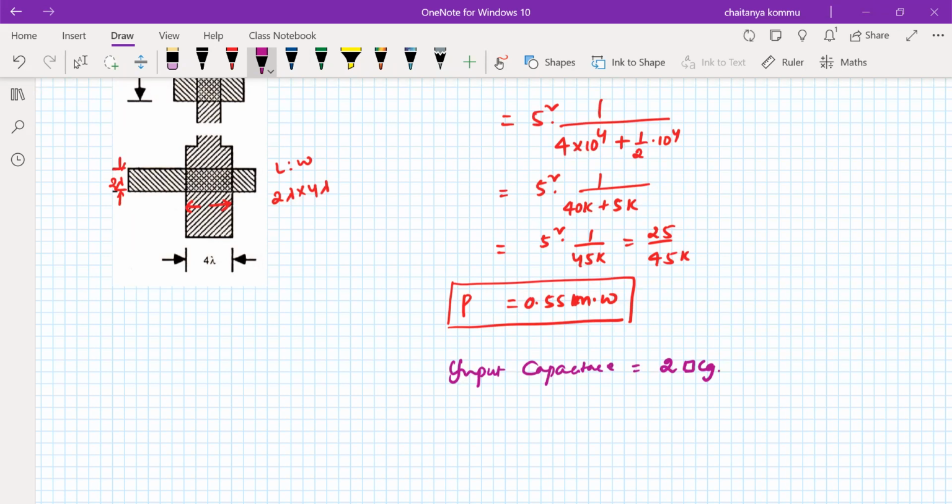How much is it increased? 1:2 is the value I have calculated. That means the length is multiplied 1 time and the width is multiplied 2 times. Whatever the multiplication factor for the width, that much input capacitance will increase. Therefore the input capacitance is directly proportional to the channel width.